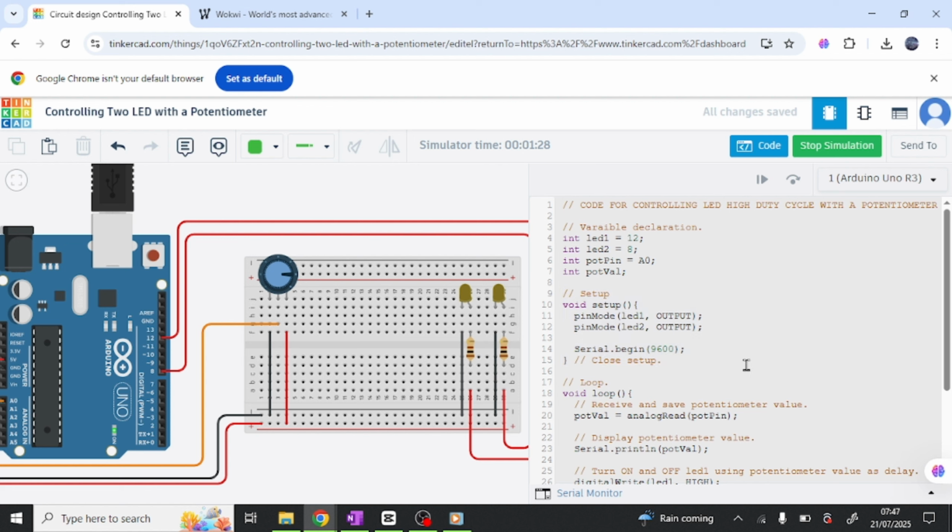The void setup is a function that returns nothing. The data type it returns is void, nothing, there's nothing like return 0 or return whatever. Setup is just the name of the function. This function is used to declare what you want the pin to do, not just to declare the pin, but to set up your Arduino. It's just like the name, setup.